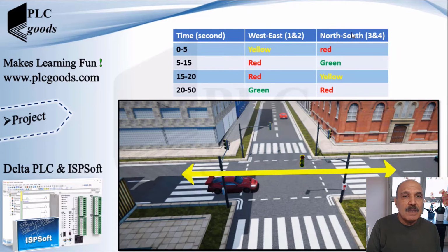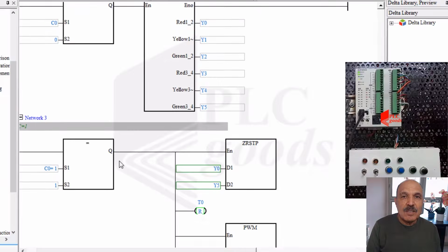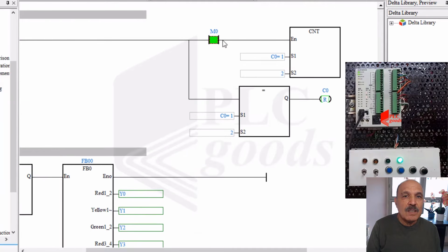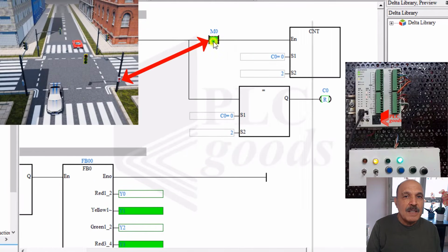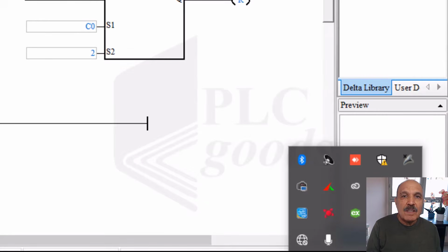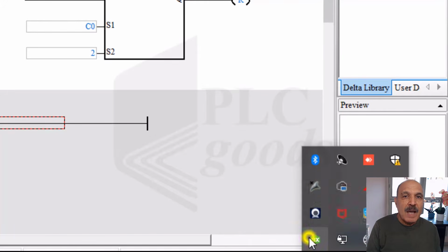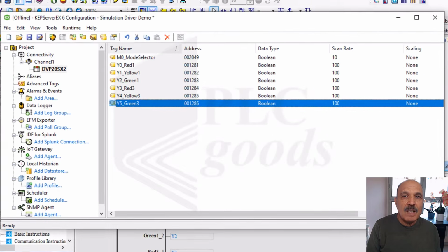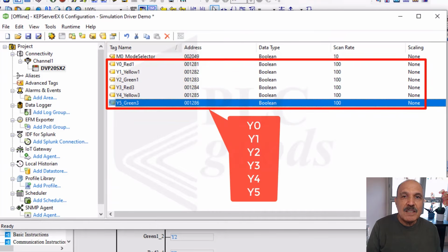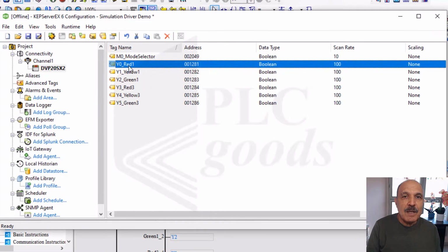We then examine the refresh and filter adjust instruction, focusing on digital input filtering. Next, we learn about the speed detection instruction, which counts pulses and calculates motor speeds, and the PLSY instruction, which generates pulses. Additionally, we examine the PWM instruction for analog control.